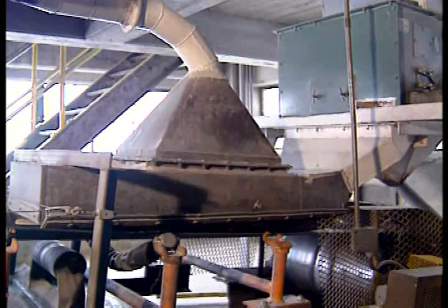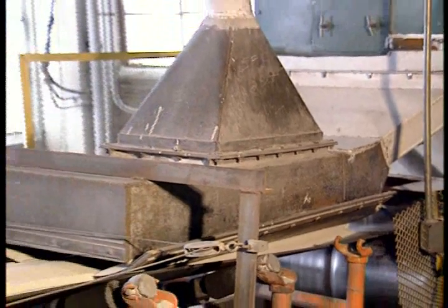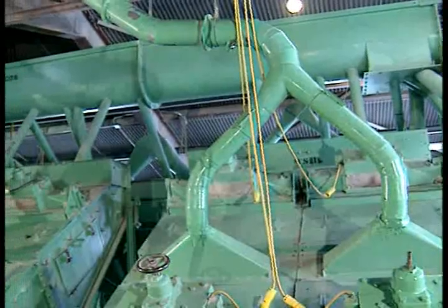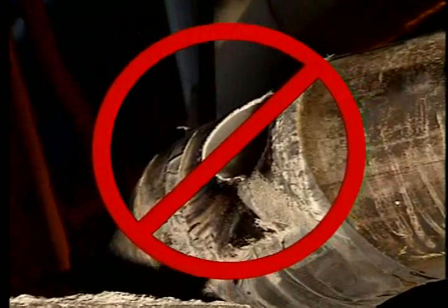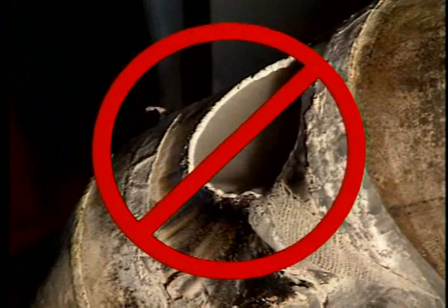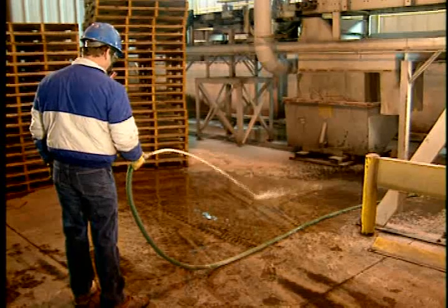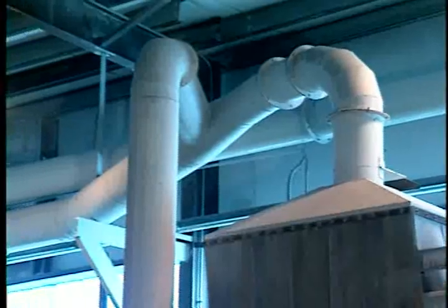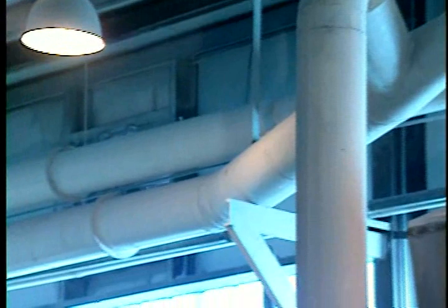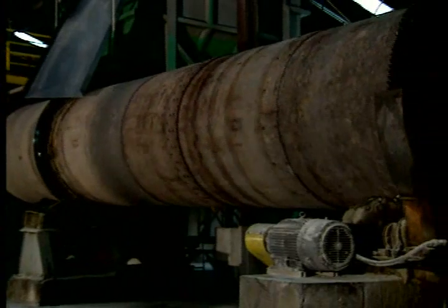Here we begin to enclose the area of a potential dust problem. You can see the dust collection and transport systems we use to minimize potential hazards. If this place weren't properly engineered, we would have major problems. We never operate with major leaks. Instead, we stop the process and fix them right away. Another practice we've adopted in this area is washing dust away rather than sweeping it up, since there would be a lot of fine dust created by sweeping. At these capture points, we've been able to capture a lot of the dust before it escapes into the plant air. But our job becomes more challenging as we move into the drying section.